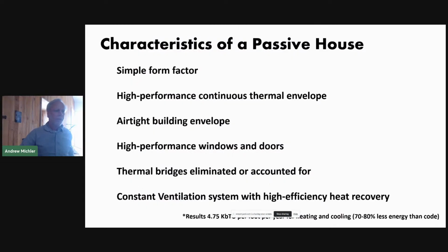And what are the characteristics? So it starts off with this idea of that simple form factor that you probably saw on that slide of the German Austrian buildings. And then the high performance continuous thermal envelope, airtight building envelope. So we need to make sure if we put lots of insulation in that we don't have air leaking through it and losing all the effectiveness. Like don't wear a parka without putting the zipper up.